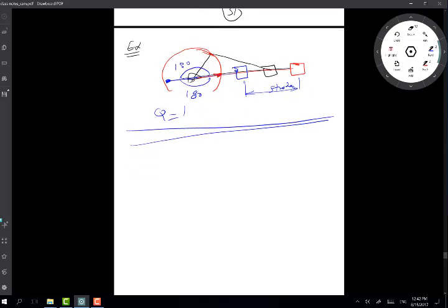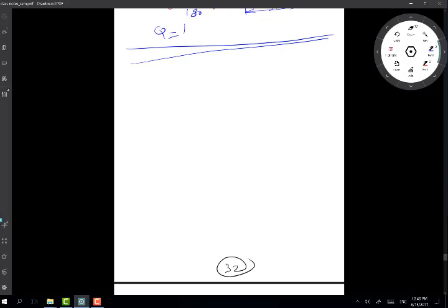Now, another interesting aspect of the 4-bar chain is referred to as mechanical advantage. Normally the input velocity is large and the velocity at the output link can be smaller, but in return, a small input torque will be magnified to a high torque at the output end. Because it's just like mechanical levers, because we magnify the torque, the linkage has a mechanical advantage. So this is one of the things you think about when you design a 4-bar chain. What is the mechanical advantage of this linkage?